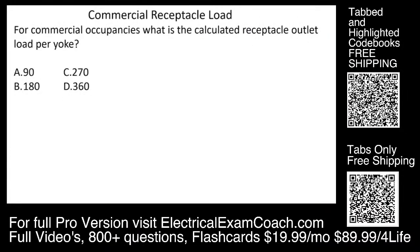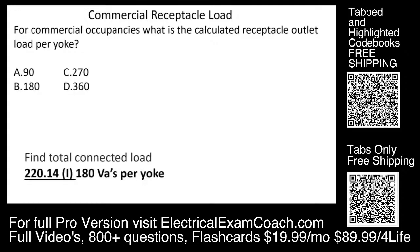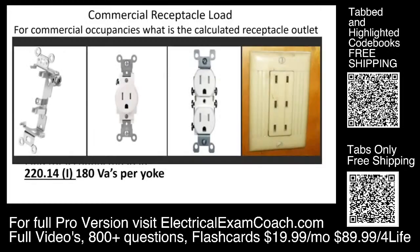For commercial occupancies, what is the calculated receptacle outlet load per yoke? First, we're going to find our total connected load. For that, we're going to head to 220.14I, and it's going to let us know that it's 180 VAs per yoke. But the question is, what is a yoke? This is a yoke. Starting on the left-hand side, it's also a device strap. It's what holds all the pieces together.